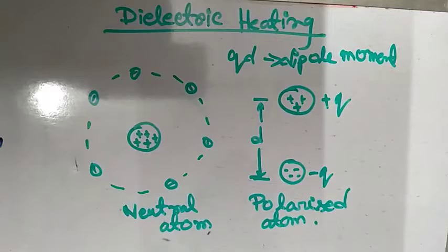Also, as far as possible, no air gap should be left over between the electrode and the specimen to be heated, as normally the dielectric strength of air is smaller than those of dielectric materials to be heated. Also, for any voltage applied across electrodes, the electric field intensity in the air gap is higher than in the specimen.